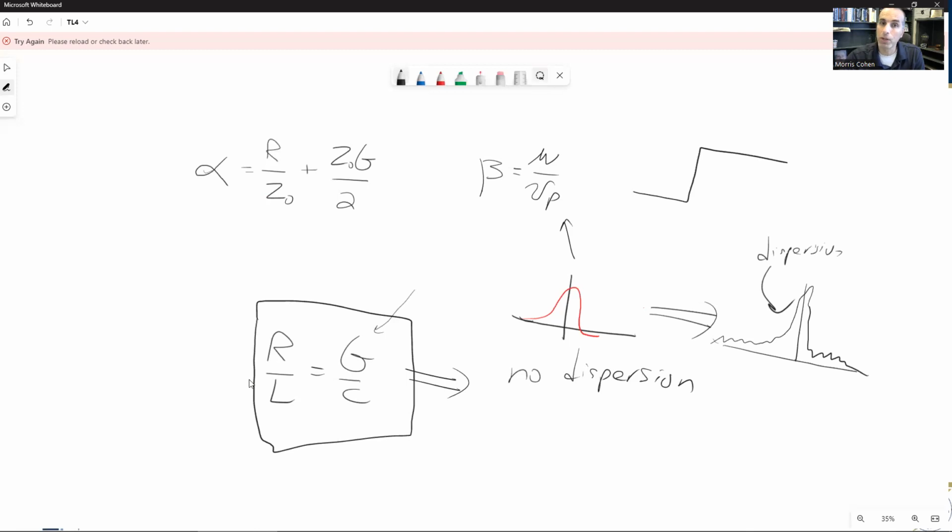And what dispersion is going to do is make the signal look kind of like this. It's going to rise a little bit slower and have a little bit of ripple on both sides, because those different frequencies are slowly pulling apart, and that's damaging. In a digital application, if we have a sharp square wave like this, the worse our dispersion is, the more this square wave stops looking like a square wave.